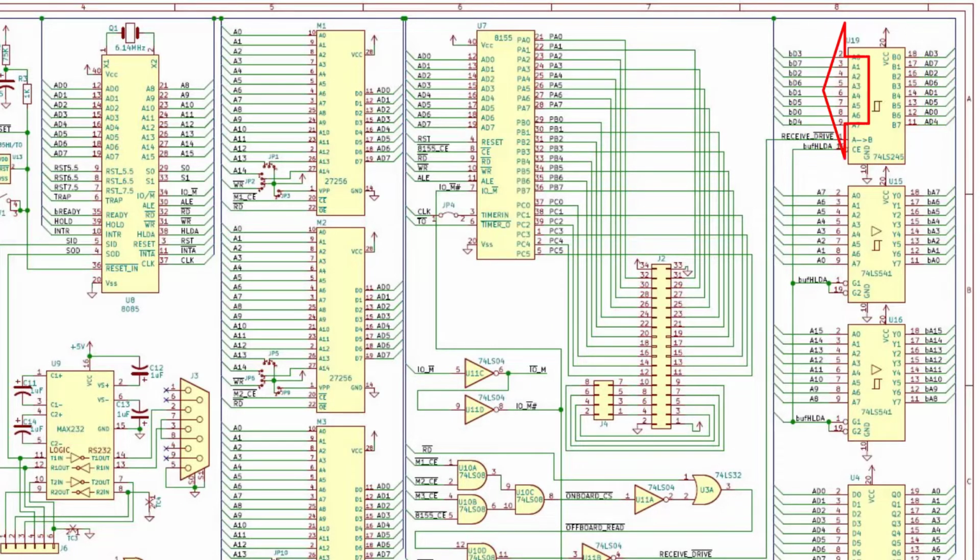So normally with this transceiver, the direction is from the onboard address data bus from the 8085 going out to the STD bus, and normally it's enabled. Unless, of course, the HLDA is asserted and then that's disabled, as I just mentioned. Putting that data onto the bus gives offboard cards insight to what's happening. It's useful, say, if you've got a bus monitor, but it's, of course, necessary for when the processor is writing to an offboard I/O or memory.